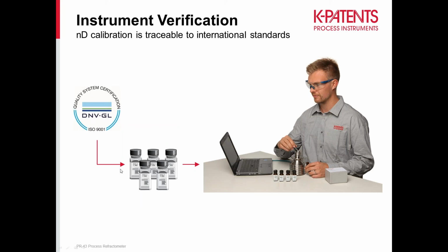That's important because that's something that to do a full verification of a density technology or tool, specifically a mass flow, you would have to put that onto a skid, and you can always measure a zero by putting water through it, but you can never do a full 0 to 100% calibration unless you take it out and put it on some kind of test stand.